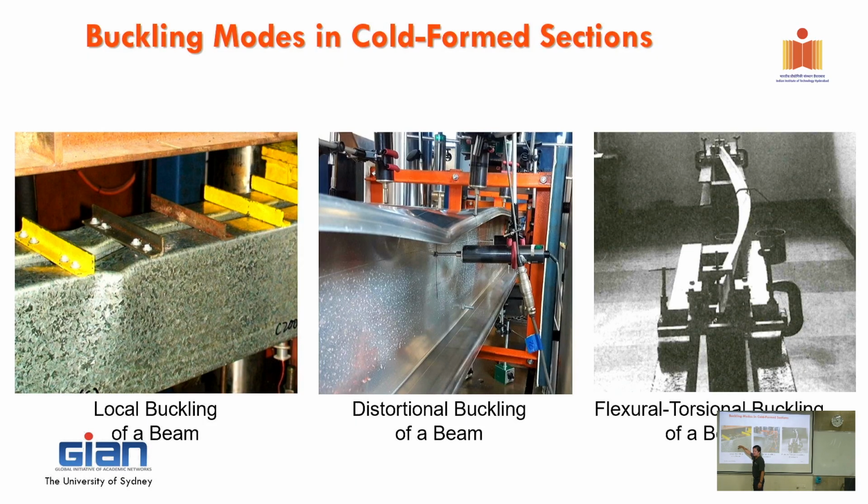So this situation is similar to the one in practice, where you have the purlin and you've got the roof sheeting sitting on top. Right, so the roof sheeting will be attached to your top flange in a way like this one. And the roof sheeting on top will help force our compression flange of the purlin here to fail in local buckling. Okay, so that's how we test it. This one, yes.